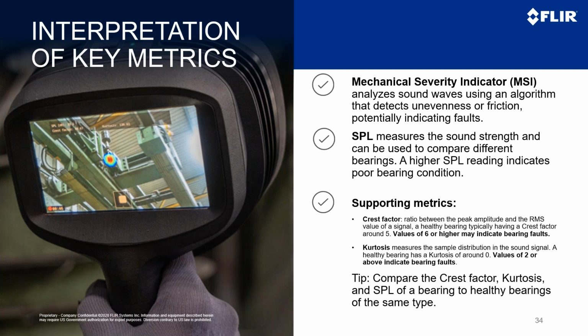So just as a tip, always compare this crest factor, kurtosis, and SPL to know the health of your mechanical component, in this case the bearing.